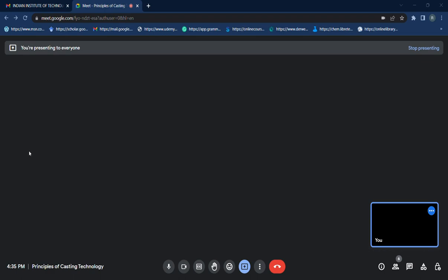And one more thing is that we put the riser in the thickest part of your casting. So we will put your riser at this part here, because this is the thickest, 45, and this is only 25. So we will put your riser here. This will be your riser. Okay, so now put riser.